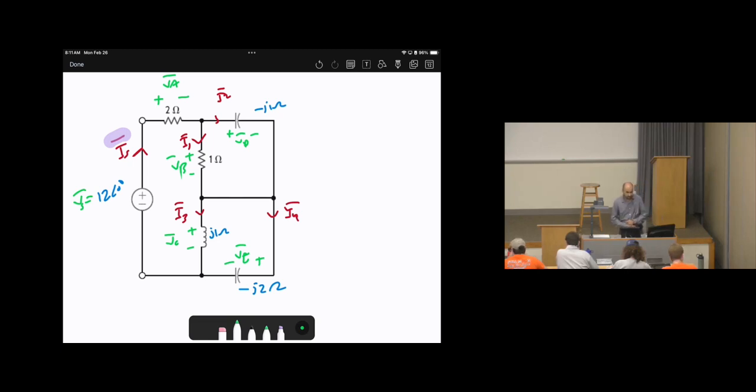Then, let's do our analysis. The only given information is the source. So start from the source side. When we start from the source side, we have the voltage of the source. Then the current is unknown. How to find the currents? Any thoughts? How can I find the current of the source? Okay, we'll start from the source side because the source is given. Find the equivalent resistance. Then after finding the equivalent resistance, we can calculate the source current.